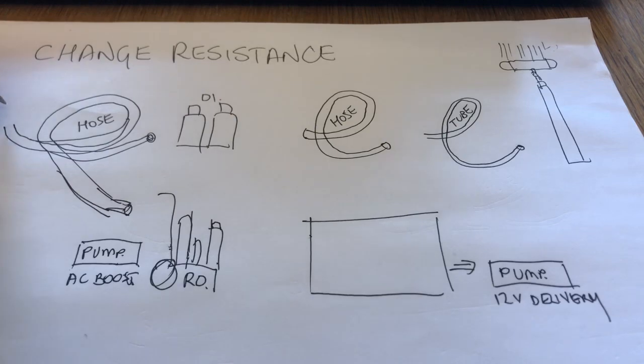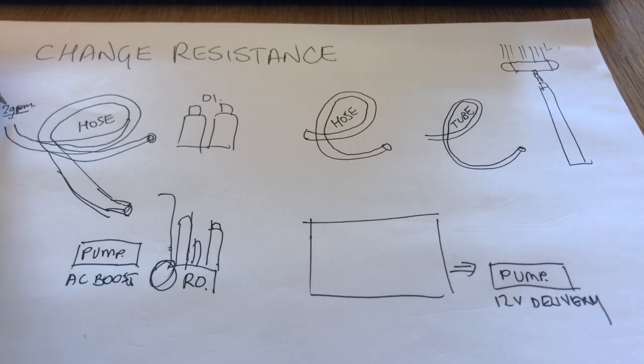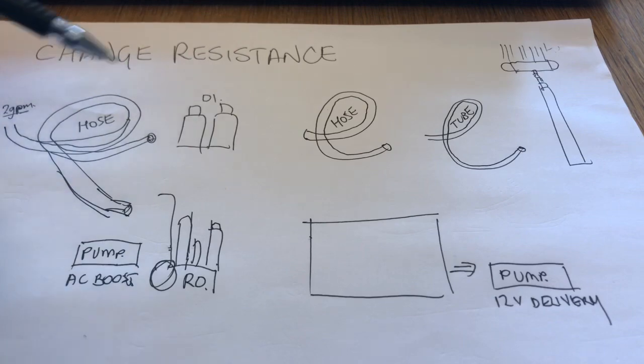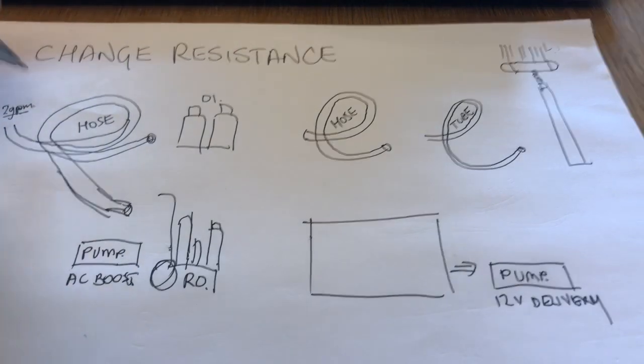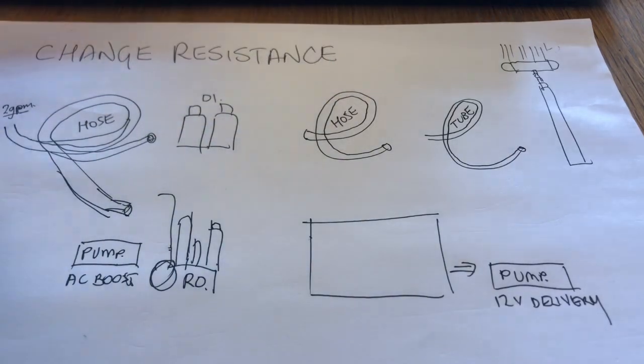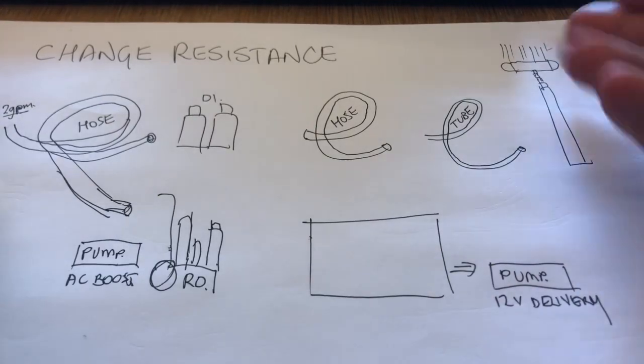And so we start with a flow rate. Let's say we start at the spigot with a flow rate of 2 gallons per minute, right? So that's critical. It's the amount of water that the beginning of your system is trying to push through your system, which creates the whole system altogether. If you only have like 0.5 gallons per minute here, you'll never get any result there because there are pressure losses all the way through.